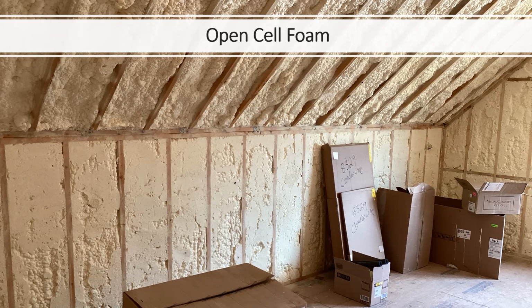Because once you spray foam beyond 2 inches, it becomes its own air barrier. It is in contact with an air barrier on all 6 sides. It's not like the open batt with trapping of the air pathways. It doesn't have to be in contact with the sheetrock in front of it. It makes its own air barrier. So those voids are okay.